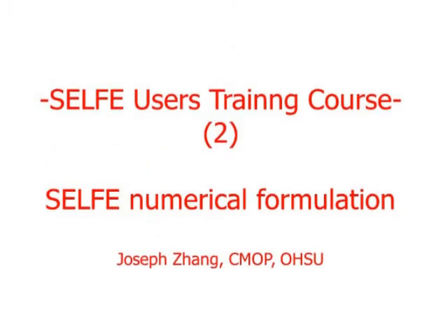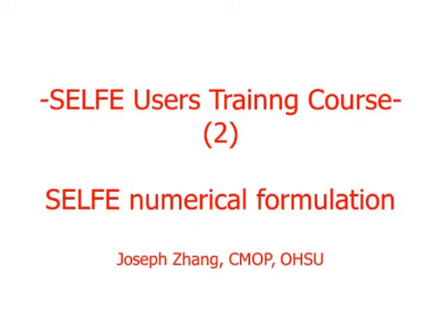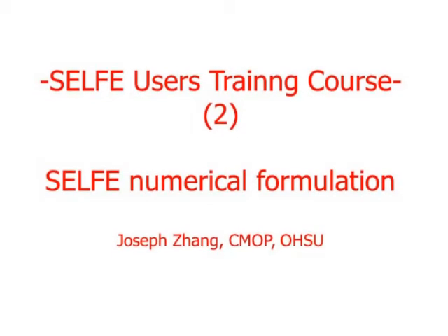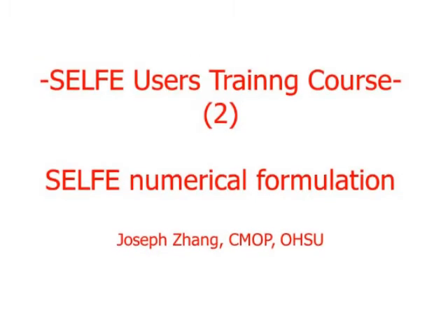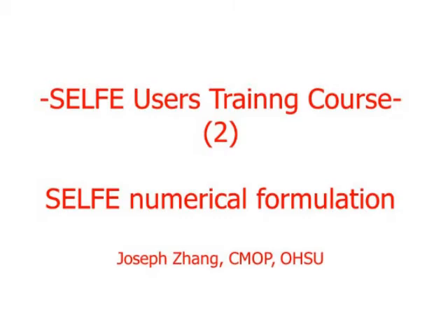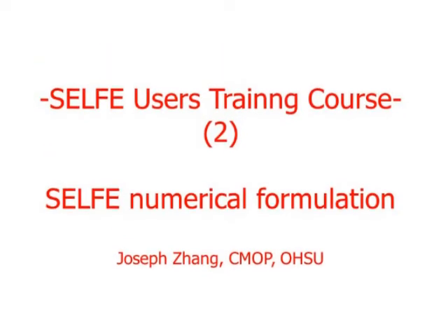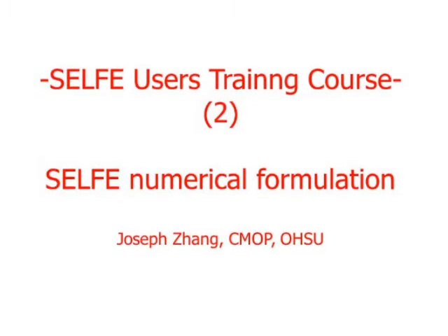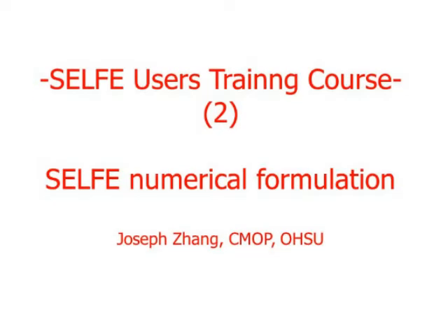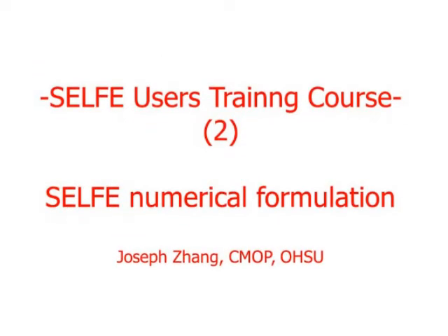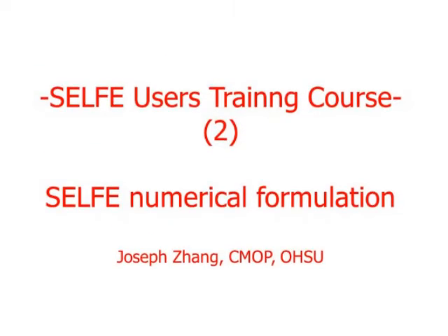So one way to bypass this problem is to use a larger albedo for the shallow region. In the newer version, we allow users to specify that variable albedo. Any questions so far? And how much larger? It just depends on your situation. Typically inside the estuary in the shallow region, say shallower than 2 meters, I just immediately jack up the albedo to about, say, 90%, 0.9.